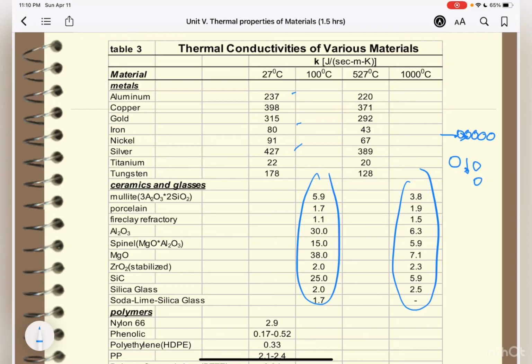So these internal pores usually contain still air, and air has a very low thermal conductivity. So these spaces of air have a thermal conductivity of just around, imagine, 0.02 watt per meter Kelvin. So heat transfer across these pores that contain still air is ordinarily slow and inefficient.